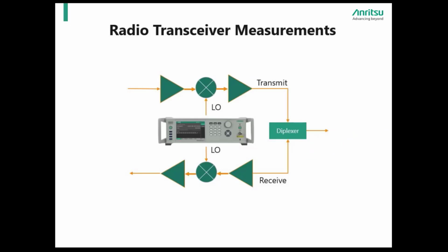The next use case is also an LO source, but for a different application which has different requirements. While the setup looks familiar as the radar measurement setup, phase noise plays a different role in this measurement. A pure LO source is essential to test IF up and down converters in transceiver chains. Phase noise is especially important and critical when higher order complex modulation formats are used to send information.